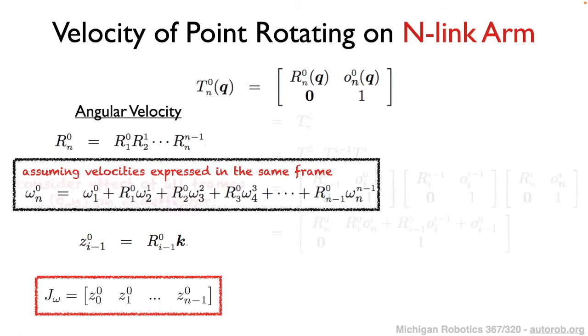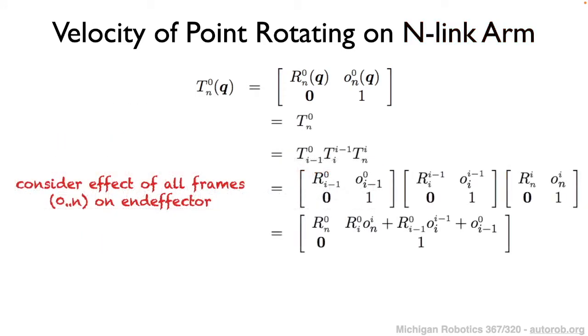To calculate the corresponding linear components of our Jacobian, we followed a similar process. If we first take our transformation from the end effector frame to the world coordinate frame based on our configuration, we can derive the composed homogeneous transformation matrix, which is shown here and should be familiar from our discussion of forward kinematics, right?